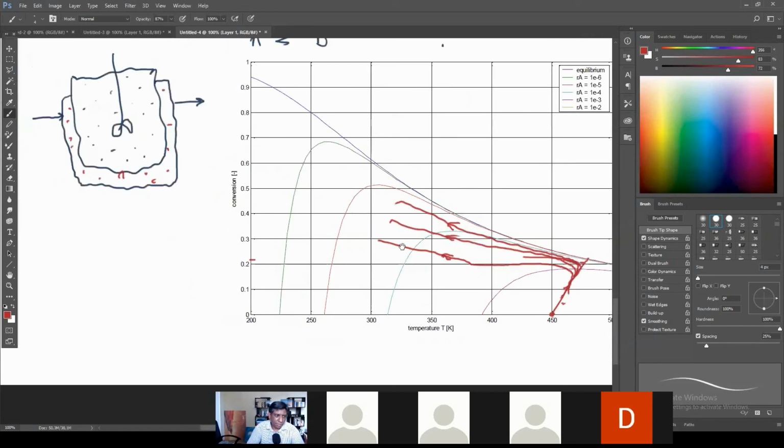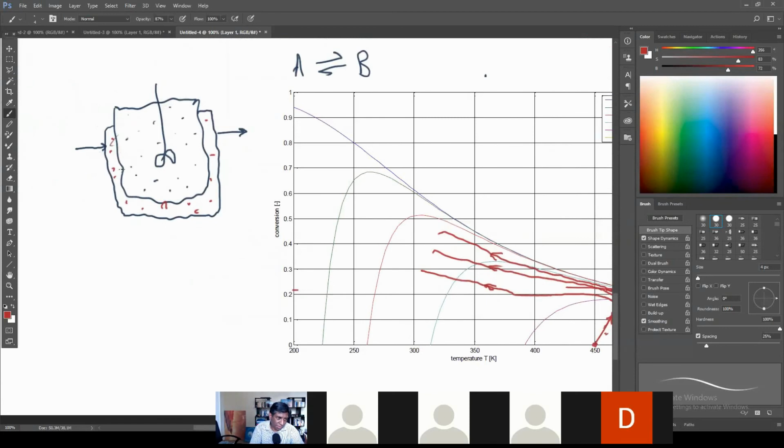So you see, in this jacket, we have control here, right? We typically have a flow controller, and that connects to some valve here. So if we apply a high rate of cooling through here, then that's going to cool this reactor down faster than if we don't use such a high flow rate.